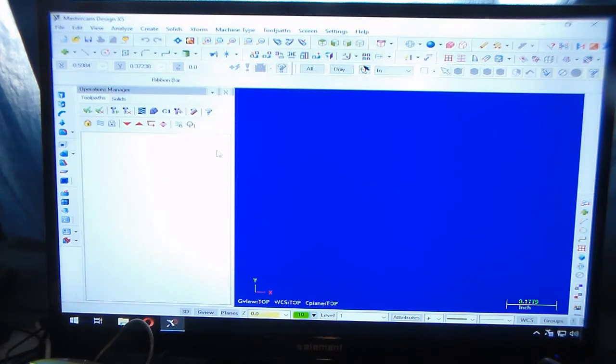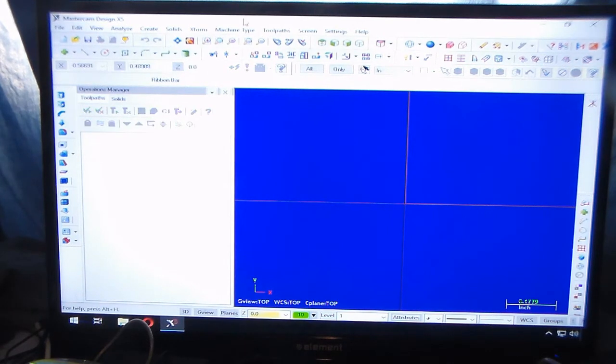Here's the cool thing about this. CNC machines run on code called G code. I could take the oldest version of Mastercam, create the G code, and use it on the newest machine. So first of all, the way you want to do this is you push F9. That gives you a grid. So machine type, I'm going to do the lathe first.